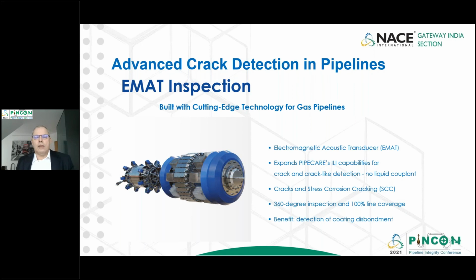This is how the EMAT tool looks like. It is a little bit similar to the magnetic flux leakage tool, which you may know. And this is because it uses a static magnetic field and also a fluctuating magnetic field to create the ultrasound inside the pipe wall. The benefit is that you do not need a liquid couplant. And an additional benefit is that this tool may also see coating disbondment.